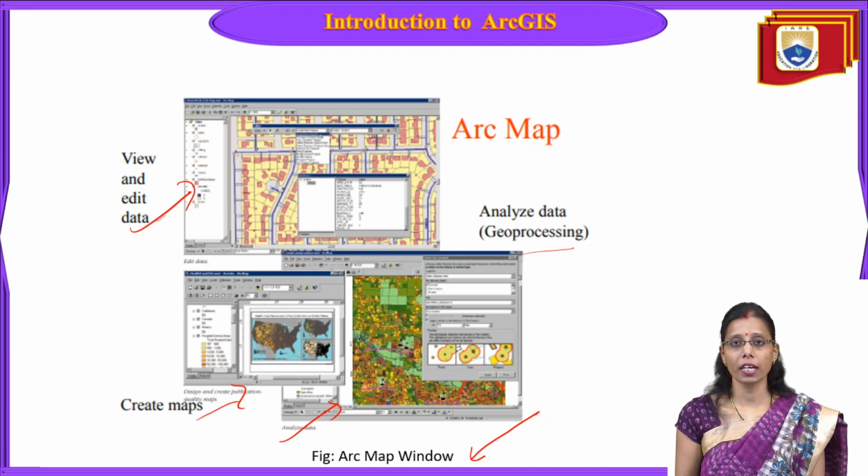So what type of data, how it is viewed. Just remember, in ArcMap the map is created. We can view the data and do all the operations. And creating the shapefile is only possible in the ArcCatalog.